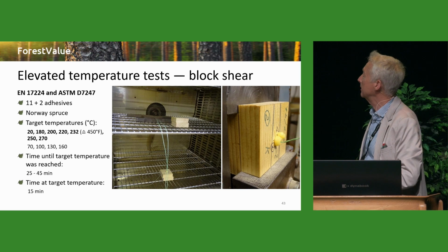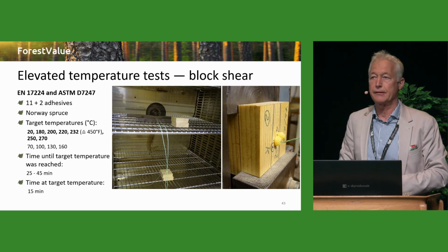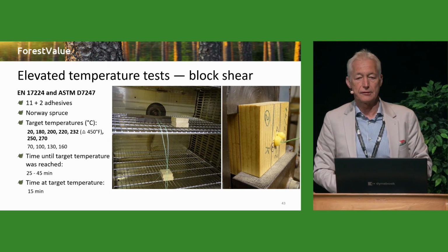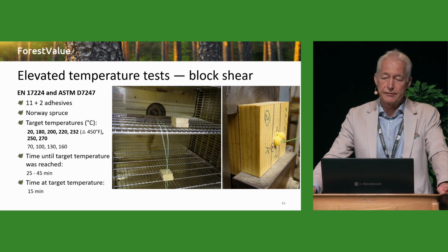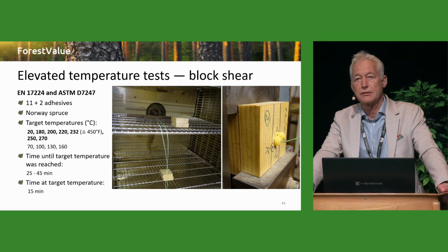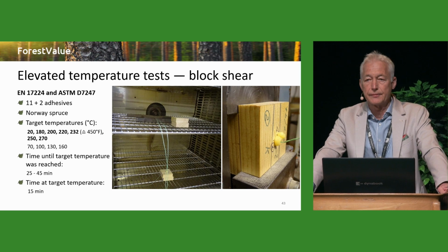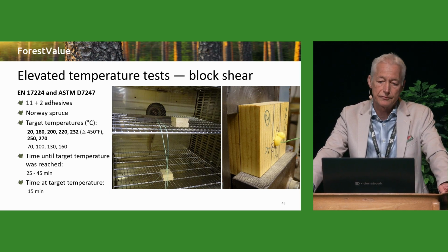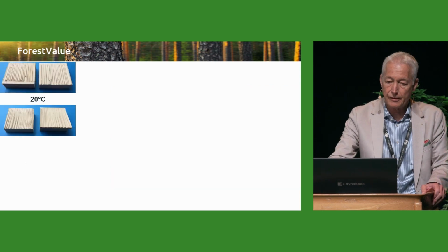What is important to say is that the specimens are pre-tempered for 48 hours at 60 degrees and have, when the test starts, whether it is at 20 degrees or 270, a starting moisture content of 1.5%.